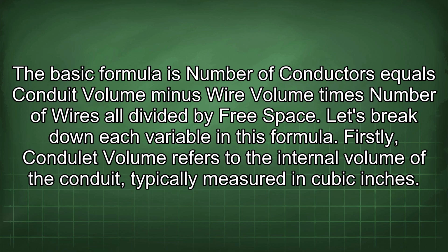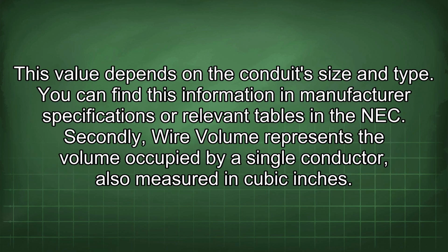Firstly, conduit volume refers to the internal volume of the conduit, typically measured in cubic inches. This value depends on the conduit size and type. You can find this information in manufacturer specifications or relevant tables in the NEC.